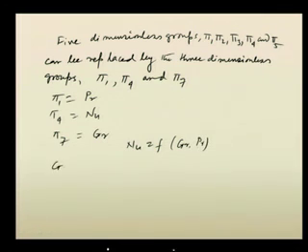Grashof number is also fundamentally defined as: we can see in the numerator is the buoyancy force, and in the denominator the mu is there, which is called the viscous force. It is the ratio of two forces, buoyancy force by viscous force.